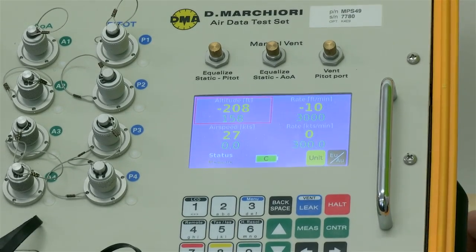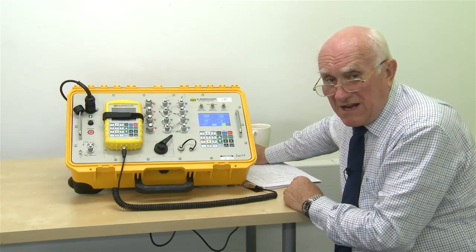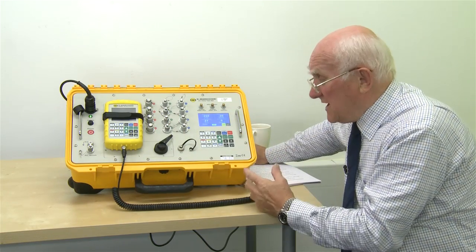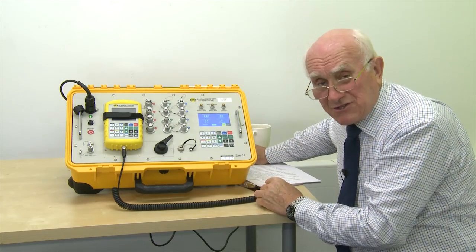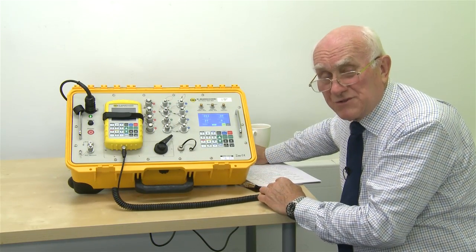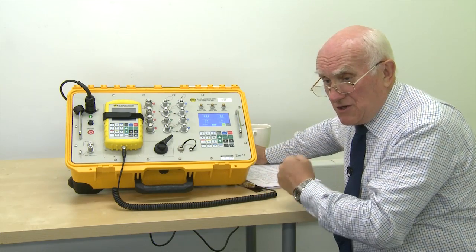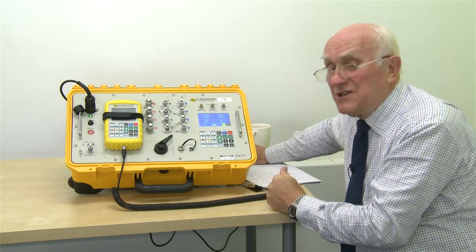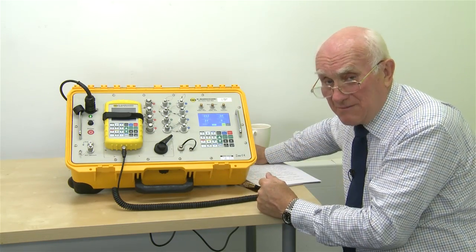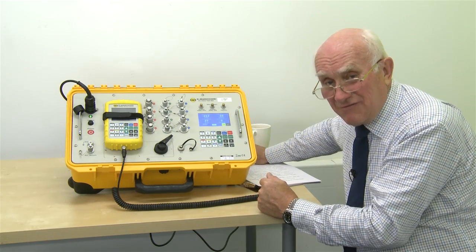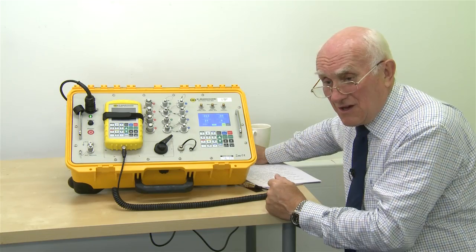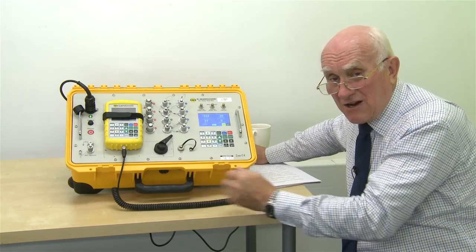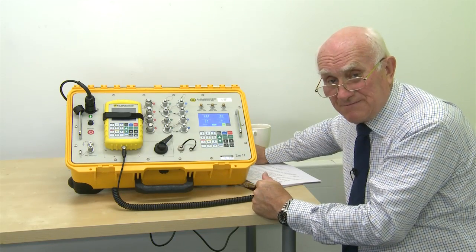We move on then to the top. They're the manual letdown valves. Generally speaking, they're probably never going to be used because the instrument comes with the capability to run on internal batteries, and the batteries will give you 2 hours of operation. This means that you can use the instrument away from AC supplies, and should you actually lose the power in the middle of a test, you won't see any difference. The power supply will take over and make everything safe, and that includes taking the test set and the aircraft down to safe ground levels.